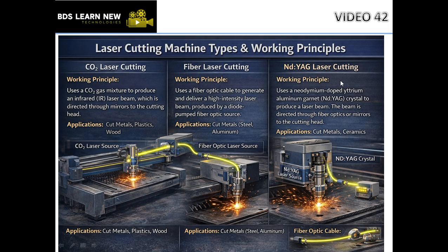Third is Nd:YAG laser cutting. What is the working principle for this? It uses a neodymium doped yttrium aluminium garnet, Nd:YAG, crystal to produce a laser beam. The beam is directed through fiber optics or mirrors to the cutting head. The applications are to cut metals and ceramics.